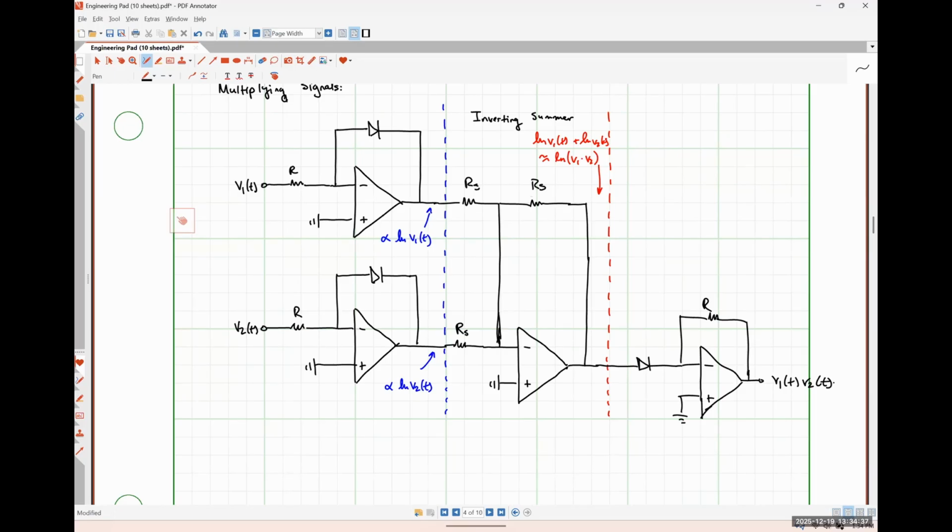Okay. If you're trying to turn a sine signal into a cosine signal and you use integration, usually whenever you integrate sine, it becomes negative cosine, right? So how does that negative play in? Does it matter? It doesn't really matter, and our integrating amplifier automatically has a negative sign thrown out front.